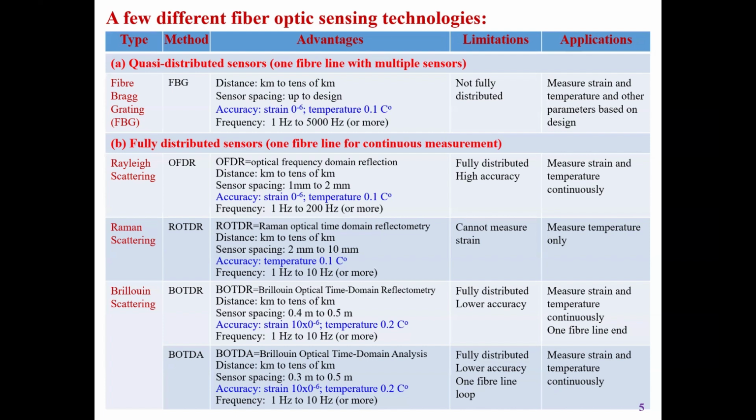Recently, we bought 2 instruments from a supplier in China. What we call OFDR, Optical Frequency Domain Reflectometry. And the accuracy is wonderful, this one. So now my group all use this one, not the other one. That's not good enough. You can see the strain accuracy, 10⁻⁶, 1 microstrain, is very accurate, not just for geotechnical structures, even for steel, it is very high accuracy.